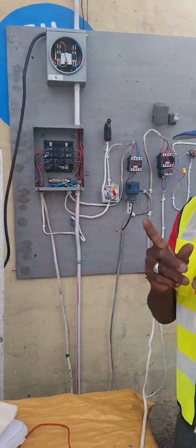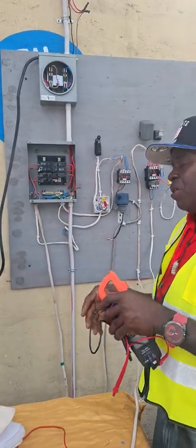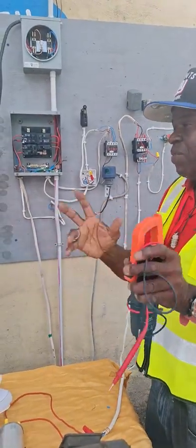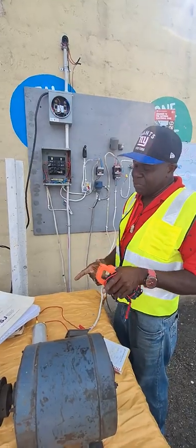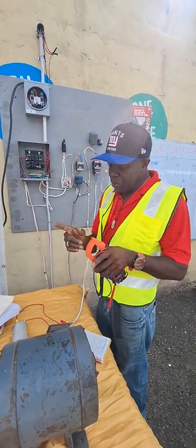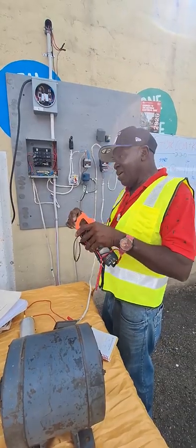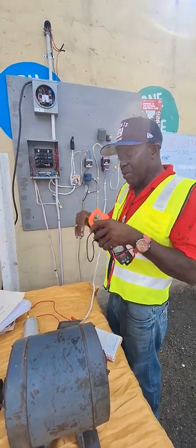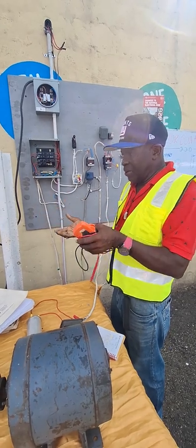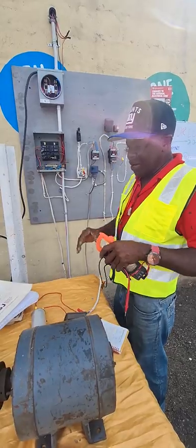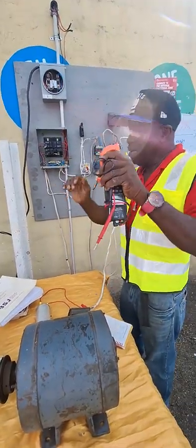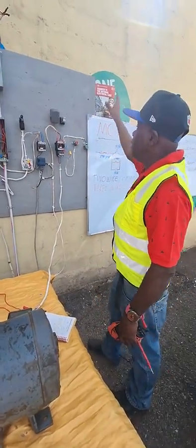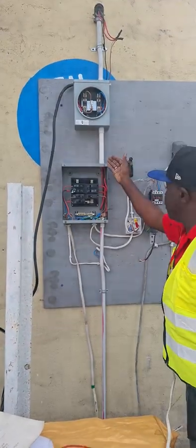You have to take into consideration the starting current and the running current where the motor is concerned. That's why they consult Article 430, I will tell you now. I believe it is 125% conductor for the motor. So 125% of the running current, that is 1.25, and you size the wire accordingly. When the motor is starting, the wire has some tolerance so it doesn't overheat. But as soon as the motor starts to run, the current drops.